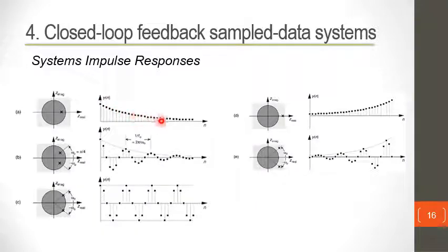So you have an impulse response of a pole that dies off like that. If it's outside, then it will just be blowing out of proportion because it's unstable. Because it's unstable, the impulse response will just go out of order.